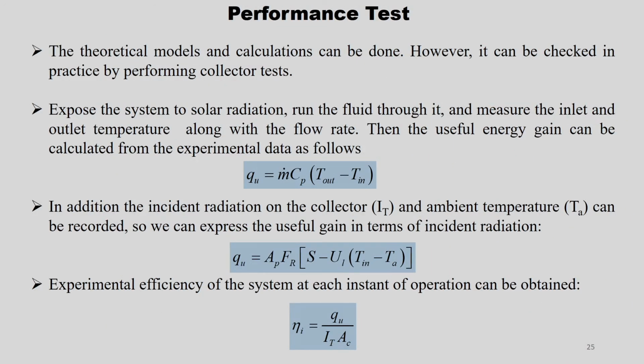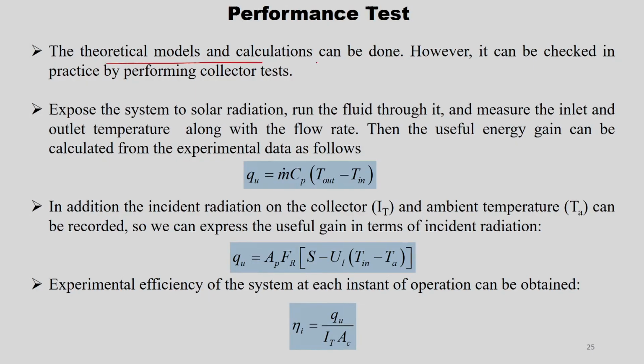So, the next one is the performance test. When you are getting a new collector, how to test its performance? That is what we are going to see here. The theoretical models and calculations can be done, which is what we have discussed till now, how to get the useful heat gain Qu, UL, Fr, so that I can directly calculate the instantaneous efficiency.